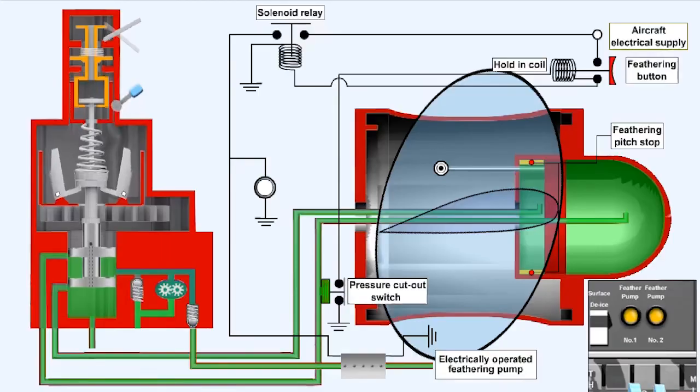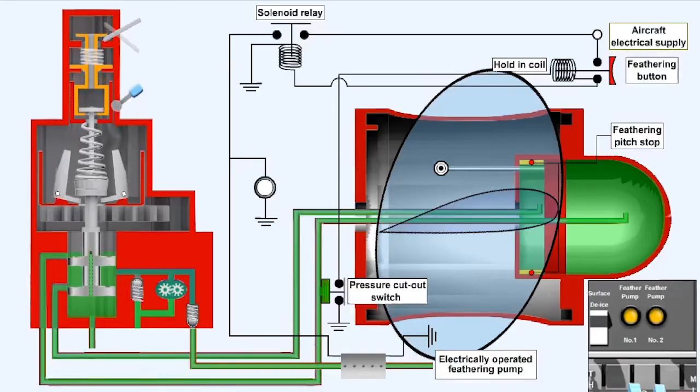The propeller control lever of the unit being unfeathered should be placed in line with that of the operating engine or engines, and where fitted, the feathering lever should be reset. This allows the speeder spring to push the landed valve down. It also helps to minimize the yaw which will inevitably accompany the effect of unfeathering.